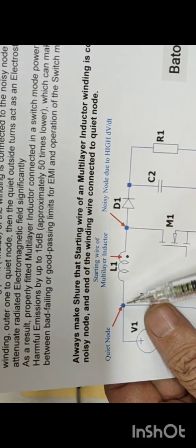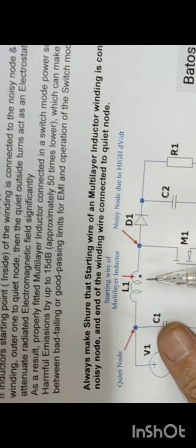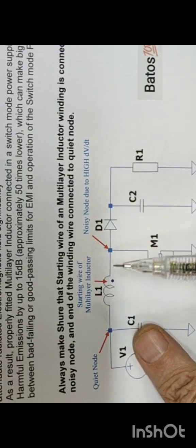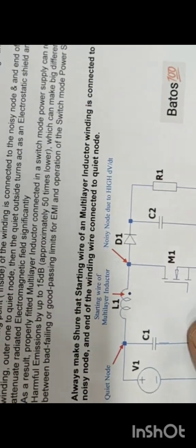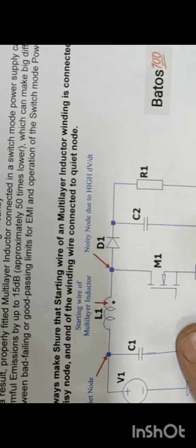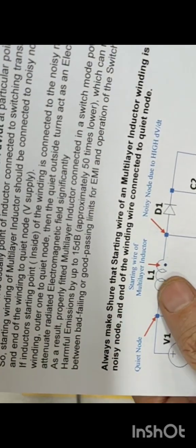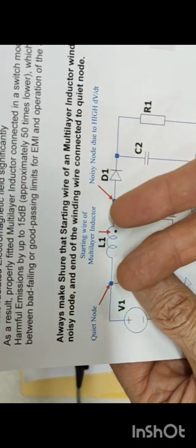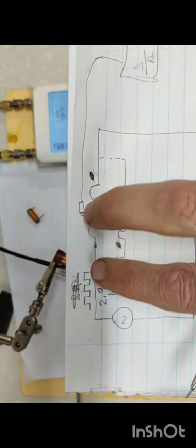It's only a pure square wave that I'm applying. So, in actual fact, the outer layer acts as a shield, and the coil starts emitting much less electromagnetic field and noise. That's why, if I reverse it and put the beginning of the winding here, then obviously my noise jumped. In other words, I just reversed the actual coil.